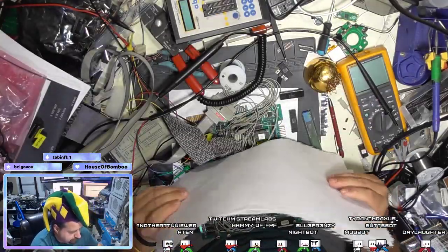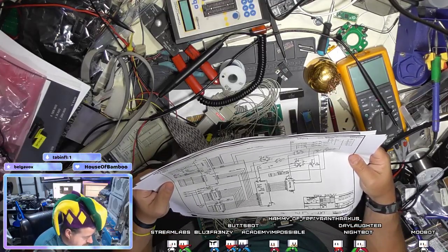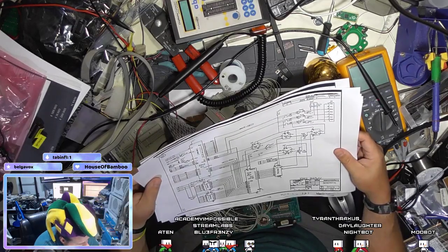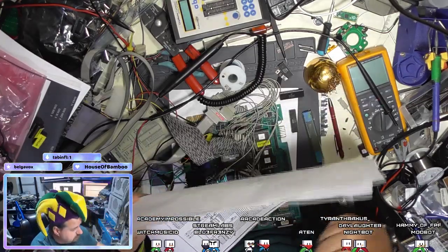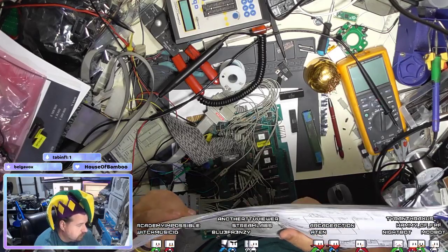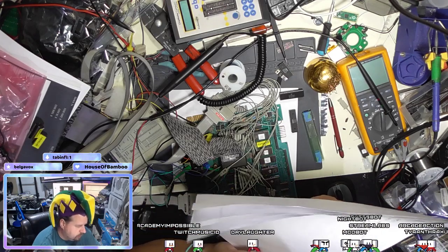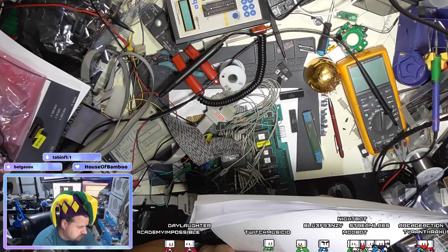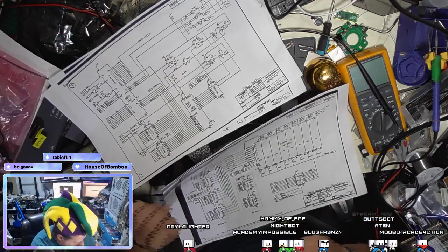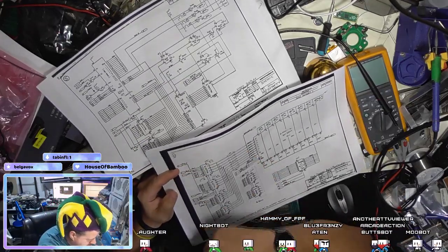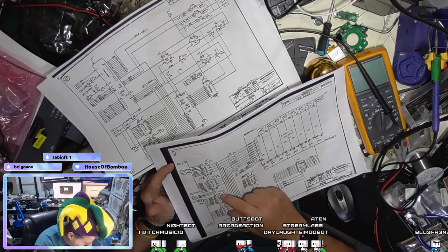Oh, MA is... Okay. MA is actually coming off of the 6545. So MA is the video RAM address. Okay, alright. Now I'm getting in here a little bit. MA here is coming from the video controller chip. It goes into these 257s. These ones here are going to the CPU.